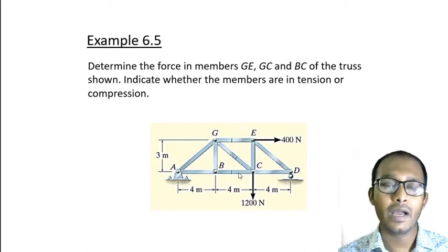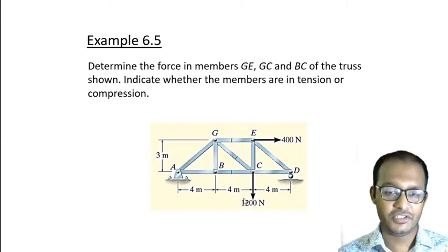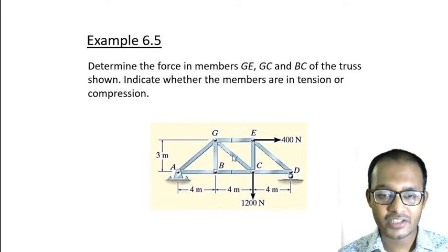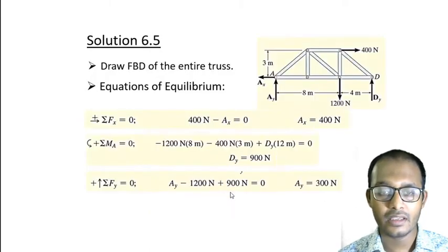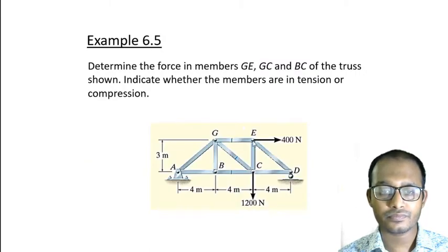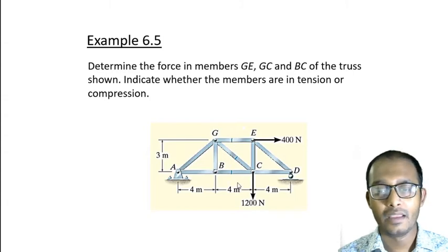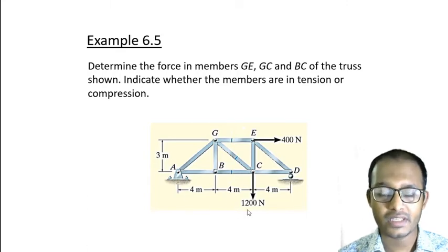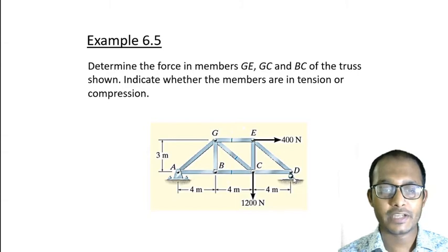Okay, so I think the force is asked in such a way that it makes it easier for you to decide where you need to make the cut sections, right? If I make a cut section from here like this, it will be very easy for me to find all the three unknown forces, right? But here we can see there is a pin joint and a roller joint in these two portions. So there will be two unknown reaction forces and one unknown reaction force.